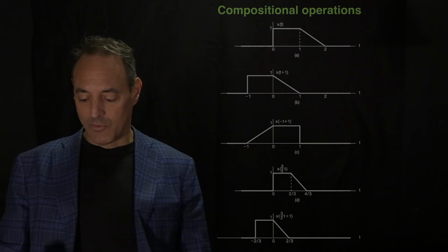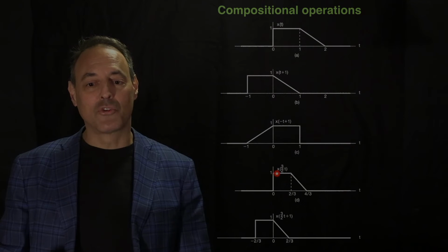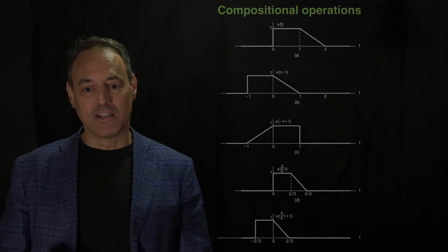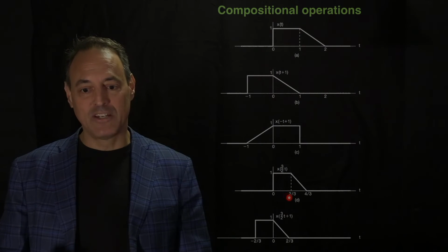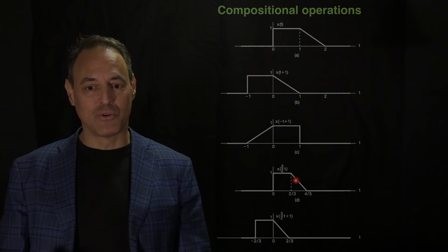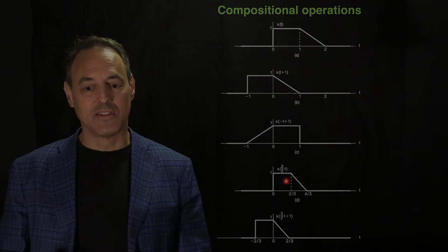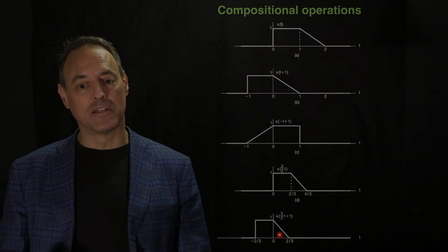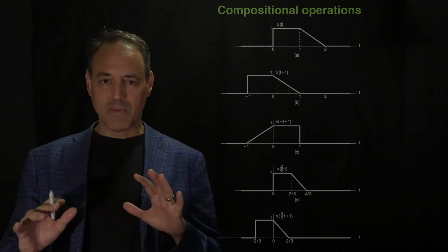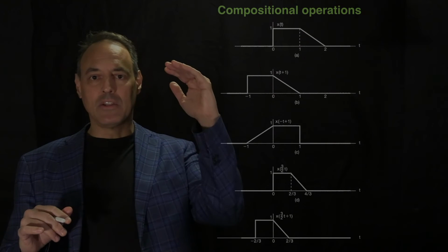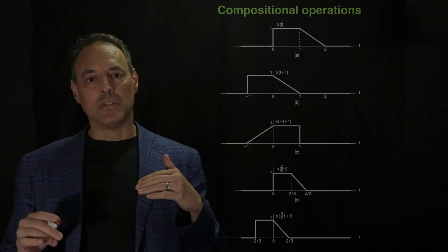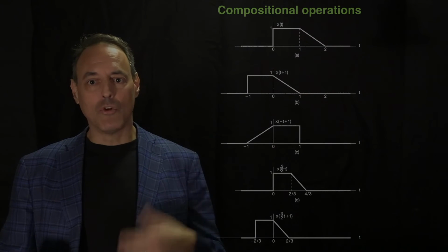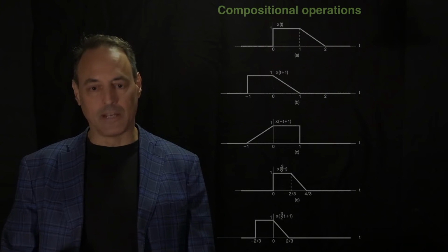After I've reflected it, we're going to scale it, so t goes to 3/2 t, and notice what it does is it takes this signal and compresses it, and notice I've got it back now to positive value, so I've flipped it back as well. So I reflected and flipped and got this signal, and finally shift it once again by 1, and here's the final signal. Okay, so all this is meant to do is illustrate that you can apply these different operations to the signal in order, and you get a new processed signal at the end of this thing.